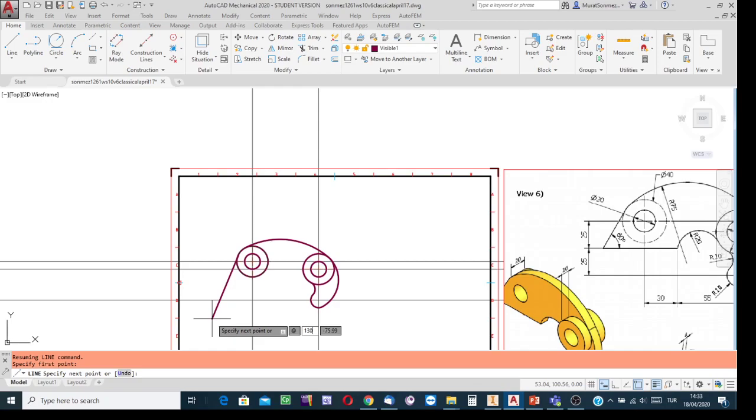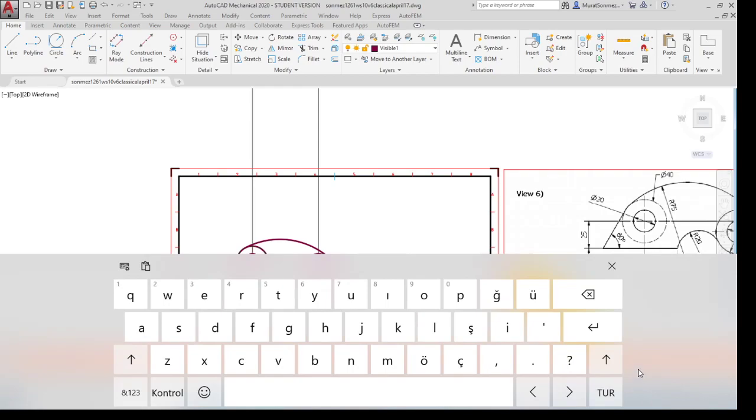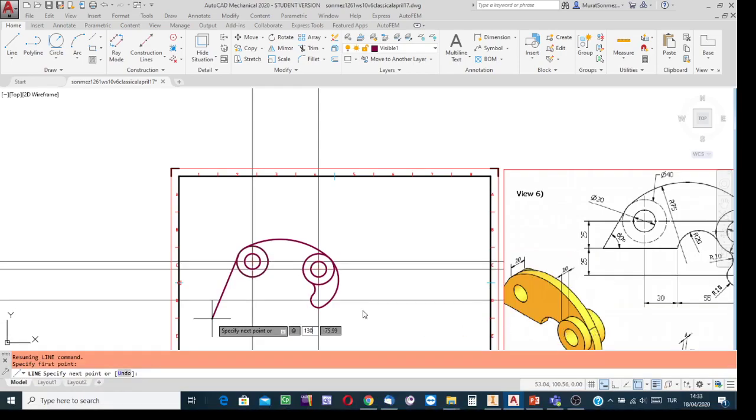Click not on the comma key, not the tab key, but on the key of the keyboard on which we have the greater than and less than symbols. Well, let me try to bring a digital one. Yes, well, unfortunately in this simulation there is no such key. Well, you know, find the key in the structure of your keyboard on which we have the less than and greater than symbols. Click on that key. It is the third trick. Clicking on that key, you see we managed to have the angle and degree symbol within the